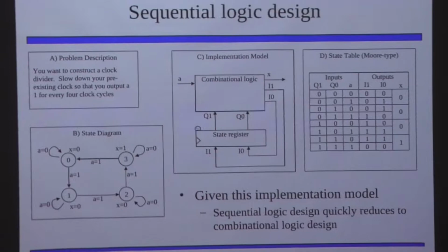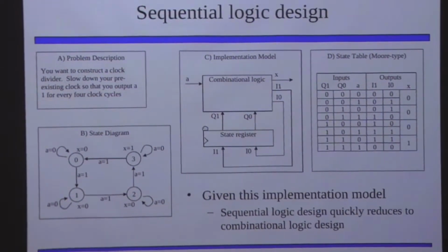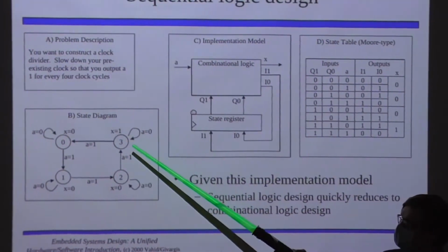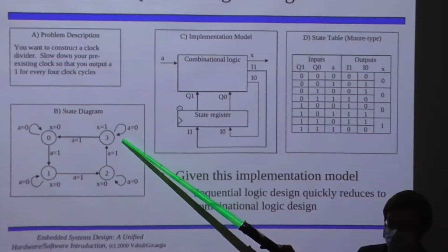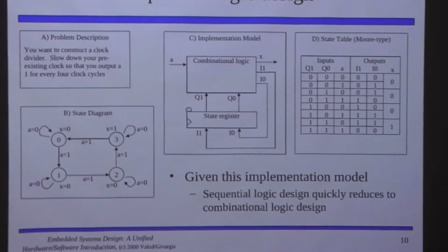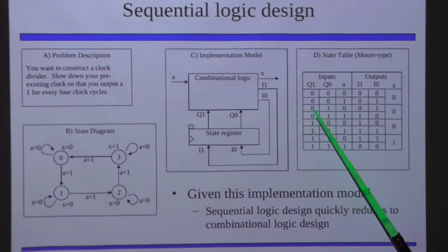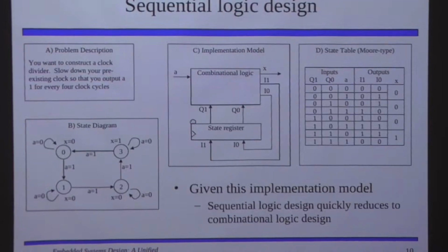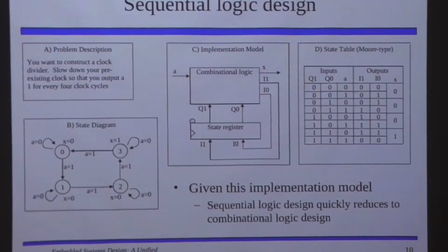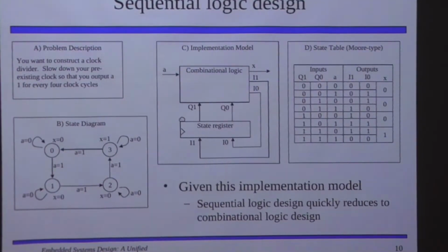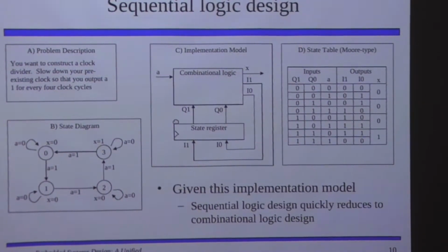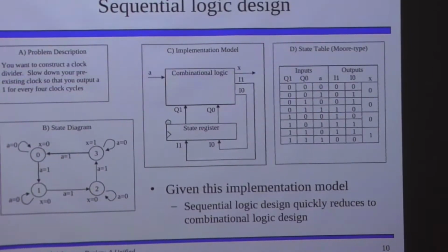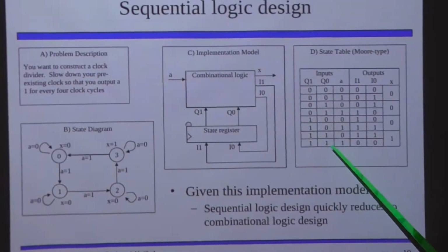If we take that and we turn it into some combinational logic, first of all, since we are storing values up to 3 from 0, we will obviously be using 2 bits to store that. In this particular example, they have chosen to represent both of those counting bits separately, which allows us to express things in pure gate logic once we get there, right? We're not going to be dealing with adders or anything at that high a level. We can just deal with gates.